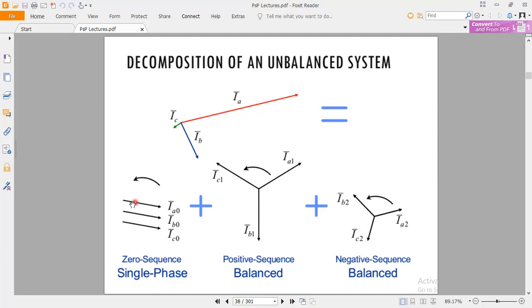Normally the phase angles are 0, 120 and 240 degrees, 120 degrees apart from each other; here that is null and void. If the phase difference is zero, then that sequence is called a zero phase sequence. A positive phase sequence is when the system is in balance mode, called a balanced phase sequence.